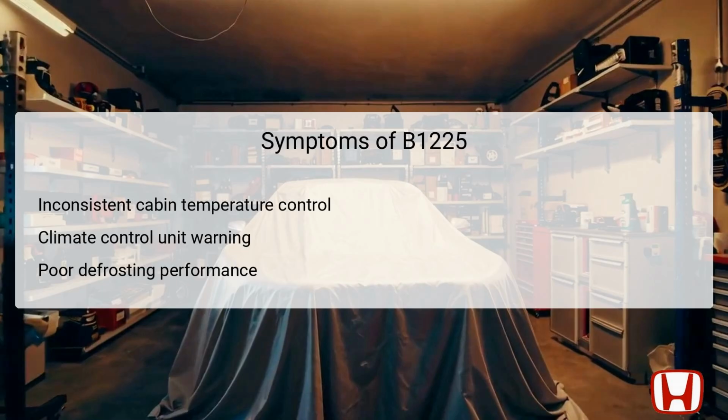Poor performance during defrosting can also be observed, as the system relies on accurate temperature readings to effectively manage the glass defrosting functions. These symptoms should not be ignored, as they signify that further investigation is needed to address the underlying problems associated with the in-car temperature sensor circuit.